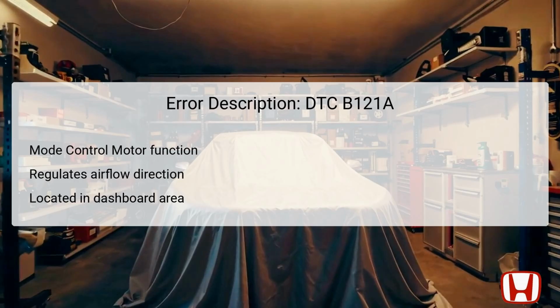If the motor is unable to receive signals due to an open circuit, it can cause improper air direction, leading to discomfort. The motor itself is generally located behind the dashboard, making it a less accessible part for service. Hence the need for precise diagnosis to locate the issue. This error can stem from various electrical failures that inhibit normal operation.